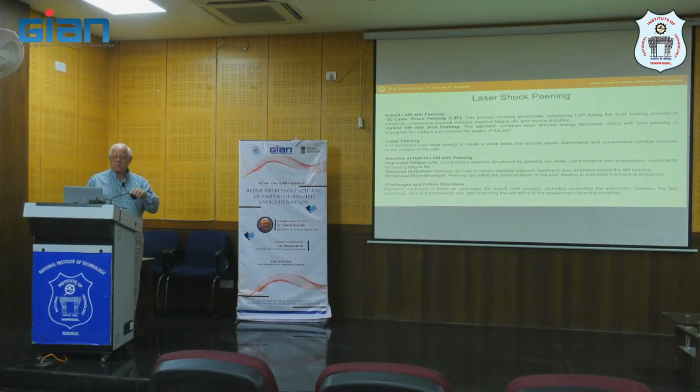Effectively, remember, it involves using a high pulse laser to create a deformation wave. This can be used primarily for lowering surface residual stresses, but also, as we'll see in a minute, for finishing as well. So again, it's a fatigue life and part performance issue.